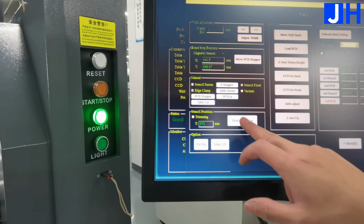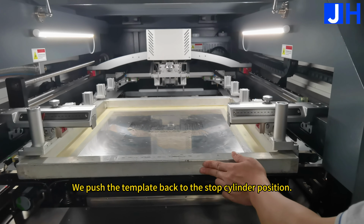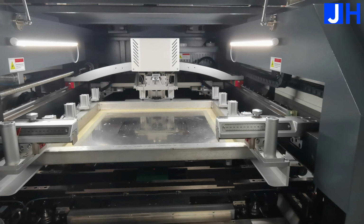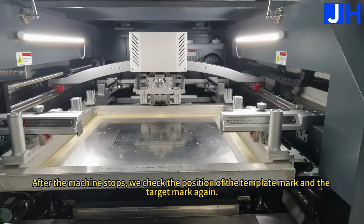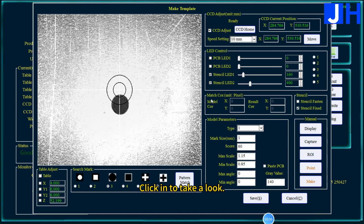Click again. We push the template back to the stop cylinder position. Click OK and the machine moves the template. After the machine stops, we check the position of the template mark and the target mark again. We click again on the template mark point parameter settings. Click in to take a look.